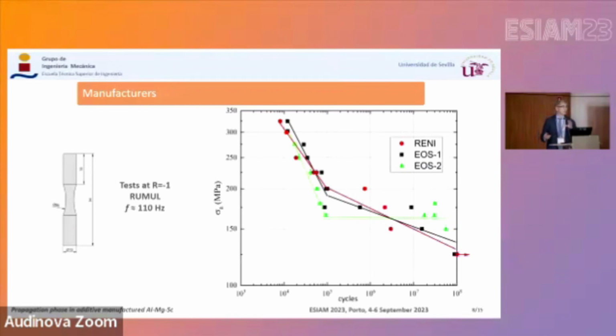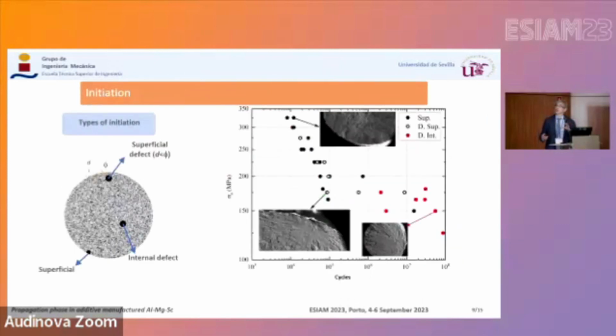Analyzing all this data in terms of where the failure started, we made this classification: failures starting from an internal defect, failures starting from a defect that was very close to the surface, and failures that started from the surface.